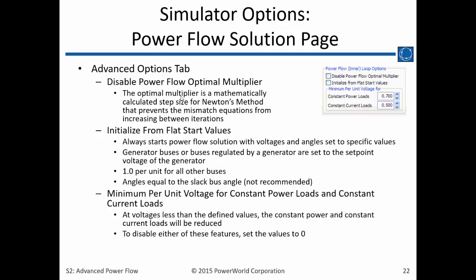That is true. We don't recommend it for a realistic load flow model or a model of your actual transmission system, because setting it to a flat start is such a drastic difference in starting point for the Newton-Raphson load flow that we typically call it a bad, or ill-conditioned, starting point. It's so far away from what you would actually have for your voltage and angle solutions all over the system that Newton-Raphson just can't find a solution for it.